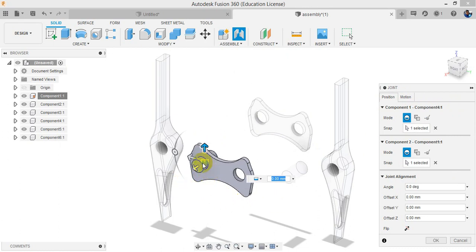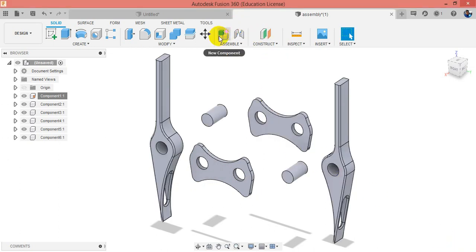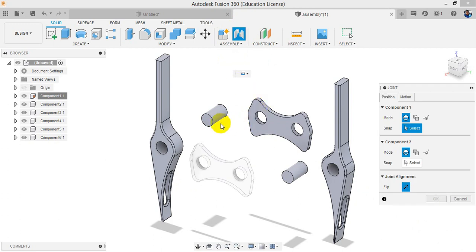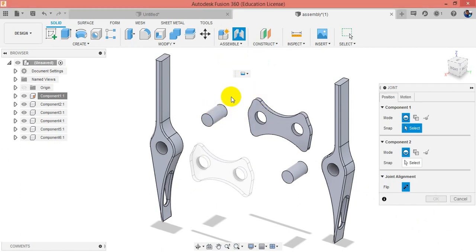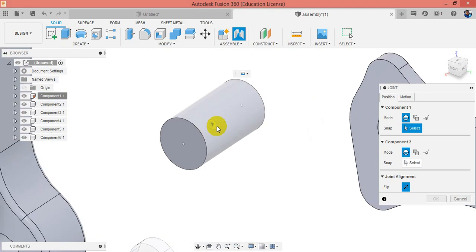What happens is that snapping the points makes them together or coincident. What that means, I am cancelling this and doing this again. You can see I can snap the points. If I zoom, you can see I can snap. When I am selecting the components, I can snap a point. It is the middle point of the cylinder or the first end or the second end, whichever, but I can snap any of the points, not the body or anything else. I have to snap a point.